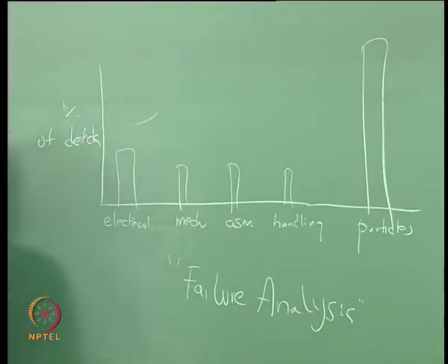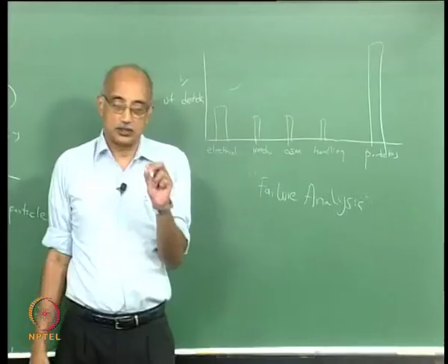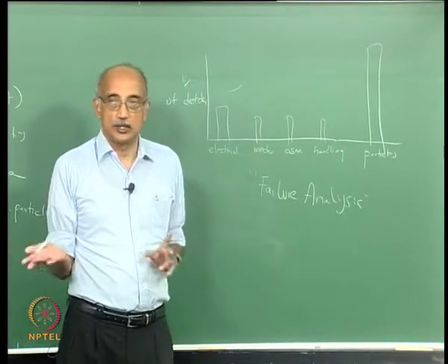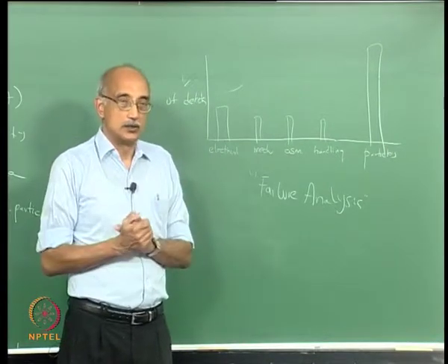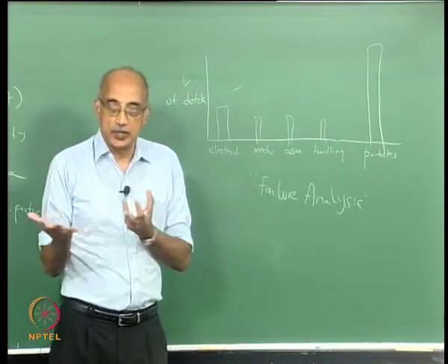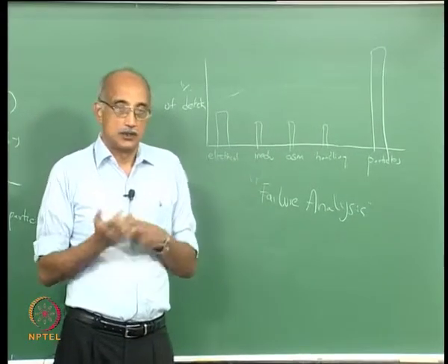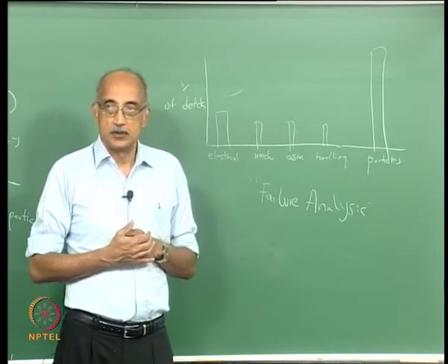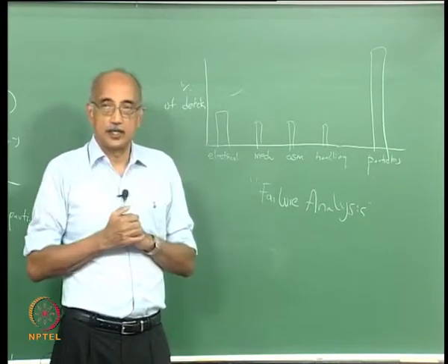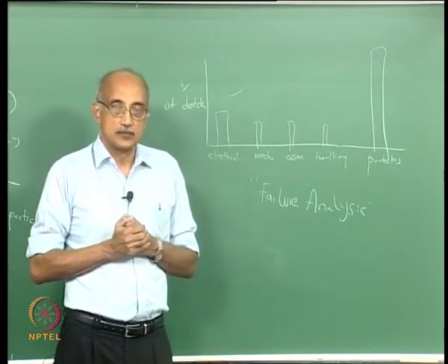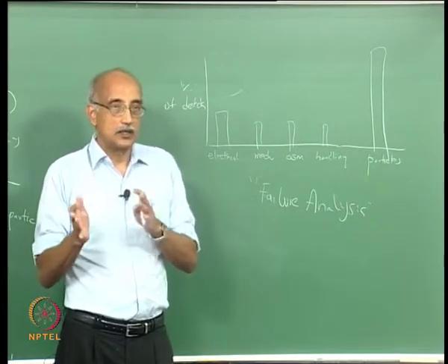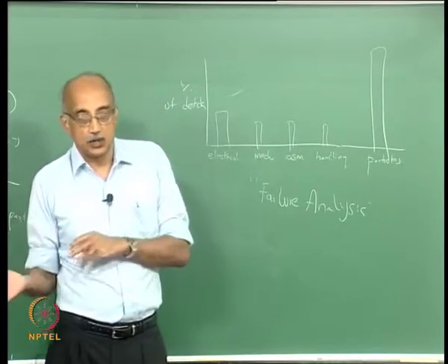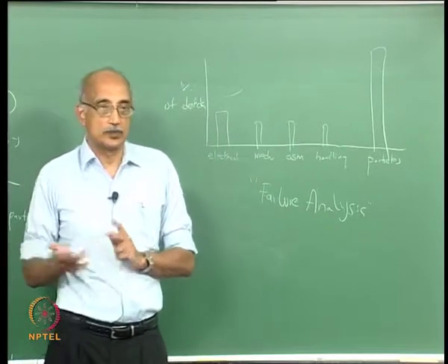Failure analysts essentially get paid to capture these particles that cause fails and analyze them to death. They do everything that we have talked about in earlier lectures. They isolate the particle, put it on a filter, bring it to an optical microscope, take a look at it, then decide is it organic, inorganic, put it under an SEM, TEM, try to get a more detailed morphology of it, 3-dimensional characterization, and then if it is inorganic, they then take it for EDS analysis and WDS and so on. If it is organic, they take it for FTIR or Raman microprobe.